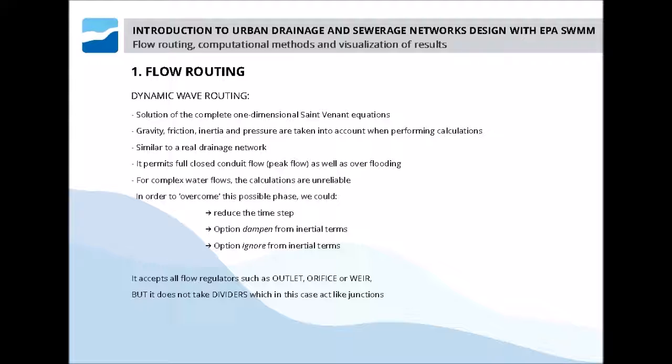The dynamic wave routing can solve the complete one-dimensional Saint Venant's equations. Gravity, friction, inertia, and pressure are taken into account. These are the forces naturally present in a drainage network. Therefore, this method is undoubtedly the closest one to reality. Because all these forces are contemplated, this method permits a full closed conduit flow as well as overflooding.